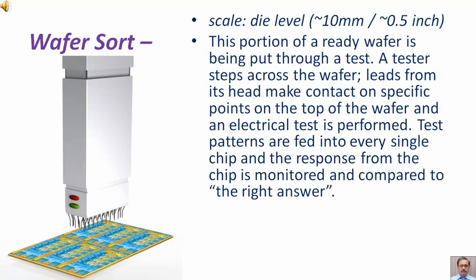A tester steps across the wafer, leads from its head make contact on specific points on the top of the wafer, and an electric test is performed. Test patterns are fed into every single chip, and the response from the chip is monitored and compared to the right answer.